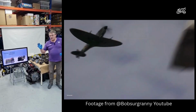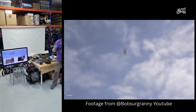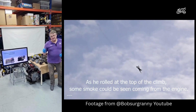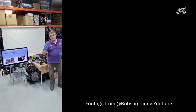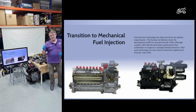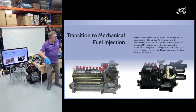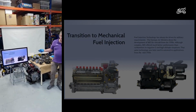So the enemy will always identify your weak point, and that was it. And so the British, at a late stage, found ways to make the carburetor work better under those conditions. So they introduced some restrictors in the float chamber, so that when the zero-G moment happened, it took some time for it to flood. It still flooded eventually, but it just took longer to flood, and that gave you enough time to do your dive and get out of it before things went bad. So, yeah, fuel injection was superior.